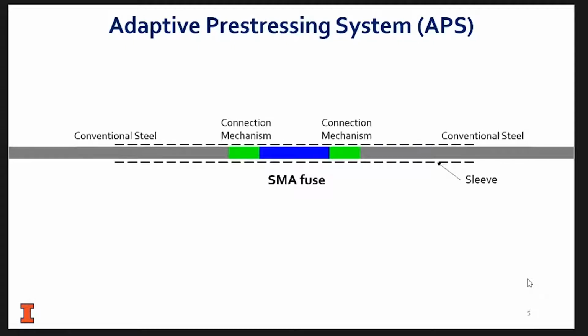Now the whole point of the sleeve really is debonding this assembly from the concrete surrounding it, because you want to enable it to move, to shrink, to breathe, in other words. Like post-tension, right? So that's the whole point of this. And then at the ends, you see here and there, I'm not sure if you can show here, we don't have a laser pointer, but it's okay.